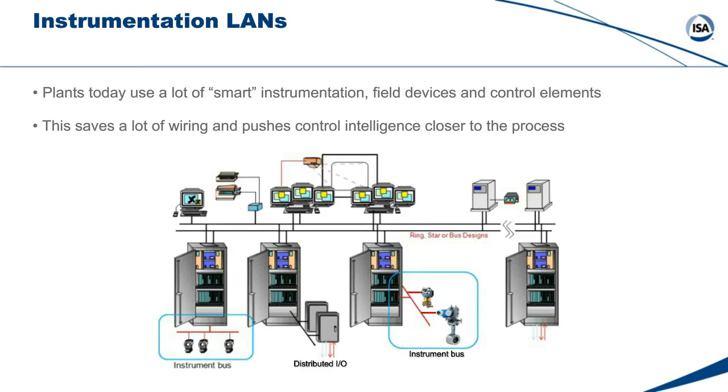Instrument buses, such as Foundation Fieldbus and Profibus, allow clusters of instruments to be connected to the control system in efficient, reliable ways. The use of HART and other smart instrument technologies allows faster, more robust communication of sensor values, configuration data, and diagnostics back to the operator station.